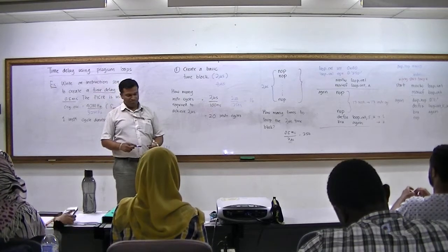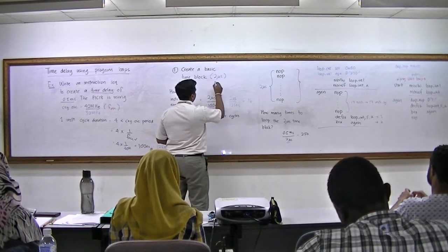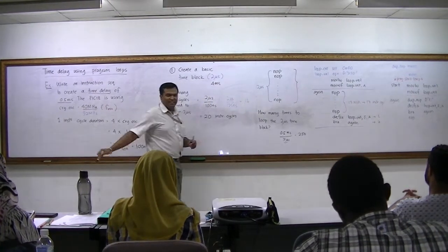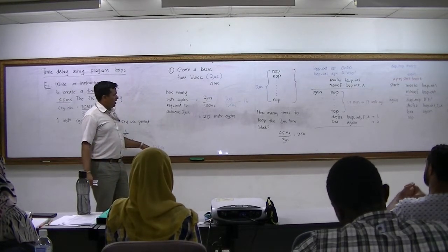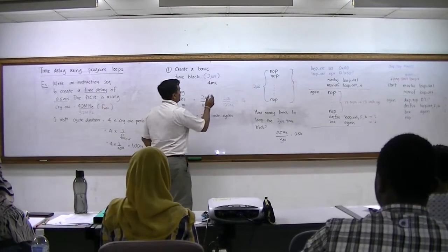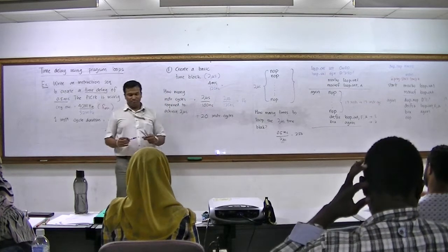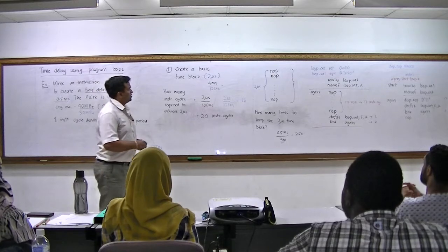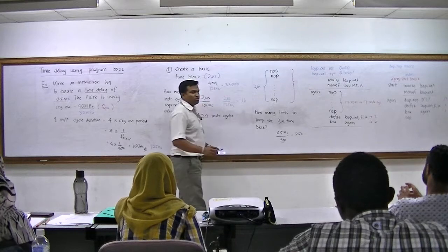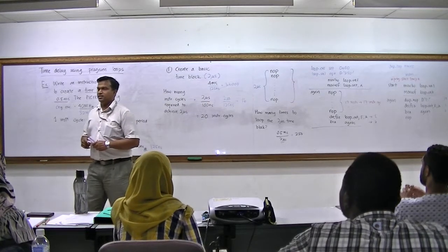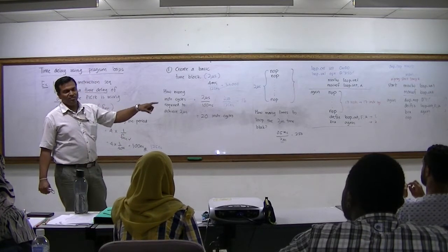Micro, milli. You want milli? Now the basic time block that you choose is 4 milliseconds. Okay, let us stick to the 32. 125 nanoseconds. So if 4 milli divided by 125 nanoseconds, how many instruction cycles do you need? 32,000 instruction cycles. The problem is, you cannot pass decimal more than 255.